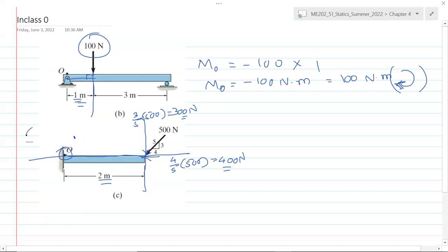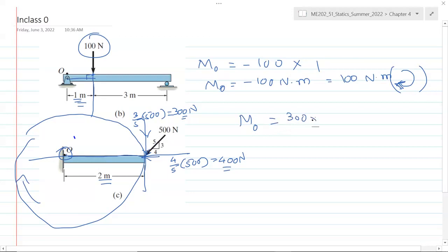If you again use our steering wheel approach, visualize the steering wheel, apply the force in the downward direction, and then the wheel turns clockwise. So the moment of force about point O is 300 multiplied by 2, and it's negative, plus 0 because of this component. So that's minus 600 Newton meter, or 600 Newton meters clockwise.